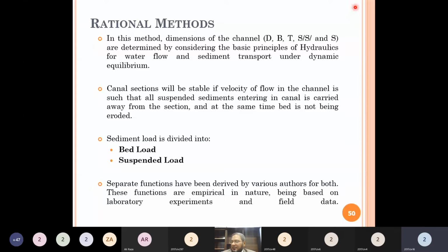यहाँ इक्वेशन मेरे ख्याल नहीं है. Okay, please write down. और ये this is given in the book of Dr. Iqbal Ali. So free board is equal to under root C times Y, where Y, what is Y? Y is the depth of flow in the channel, जिसको हम capital D भी कहते हैं, है ना? So that is the Y, depth of flow, जो आपने डिजाइन की है depth of flow. और what is C? C is a coefficient